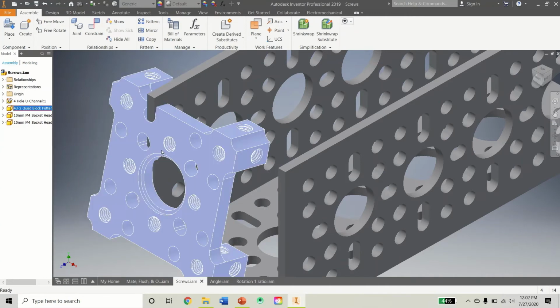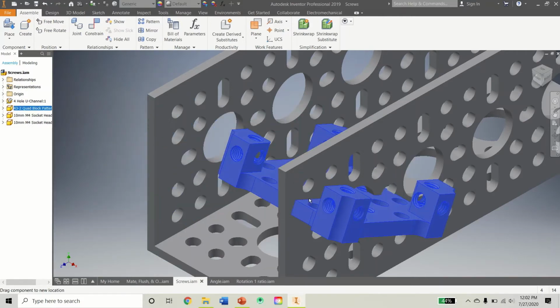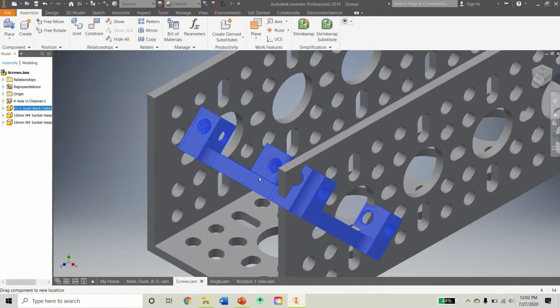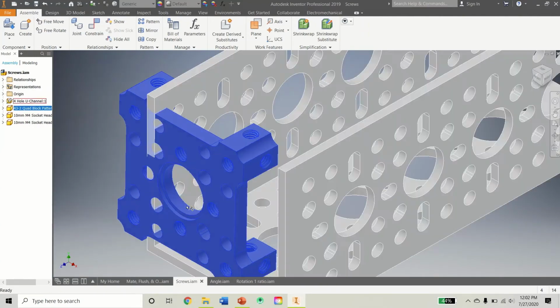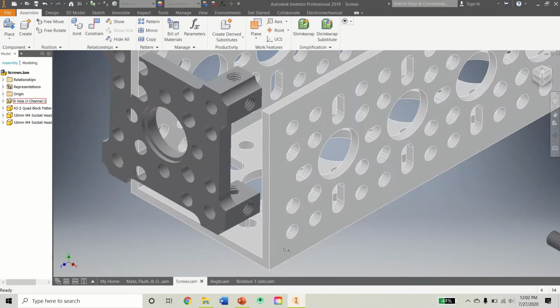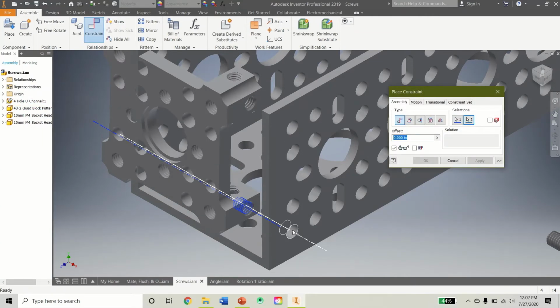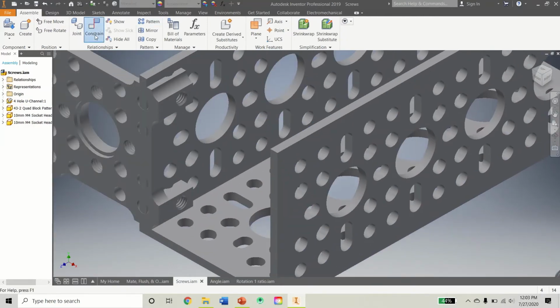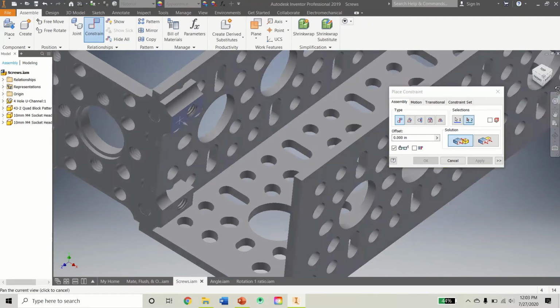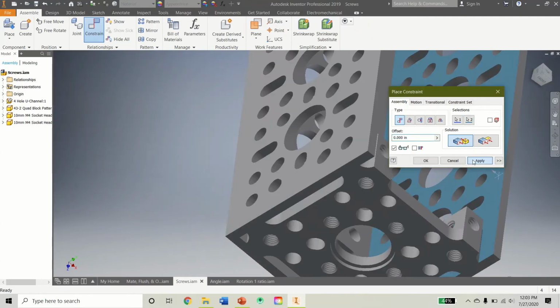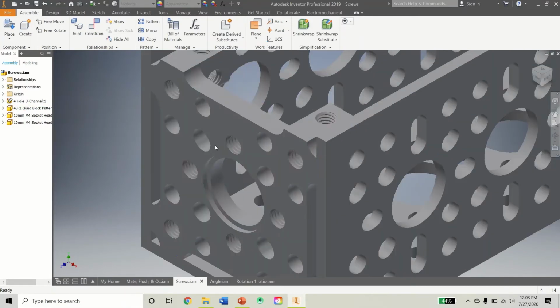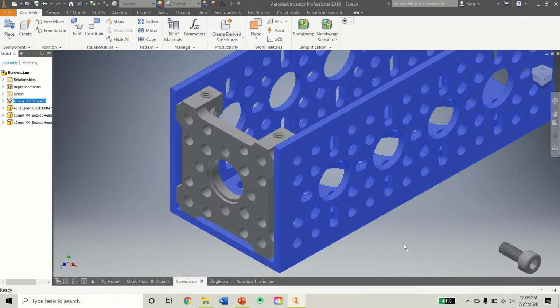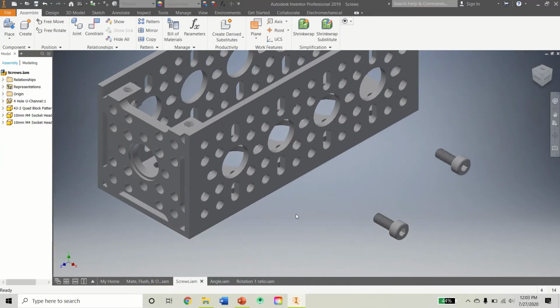So I can move that from side to side, and it will stay on the axes here, and it'll still slide around and do all its things. But now we're going to want to do those two axes there, just like that. Now it still slides around here, and as you can imagine, we have to do a mate constraint. After we do this mate constraint, this part is completely constrained inside of this grounded U channel.